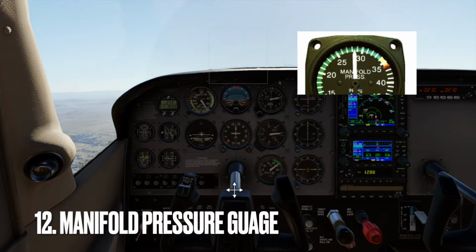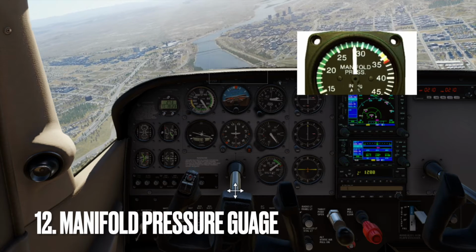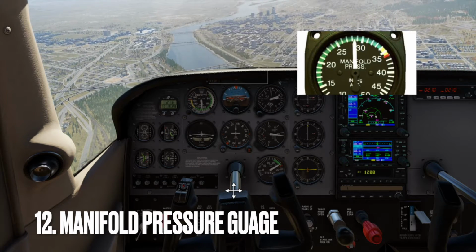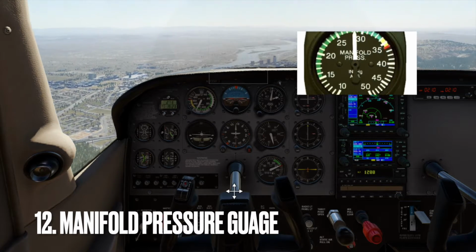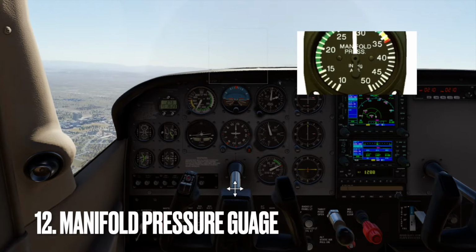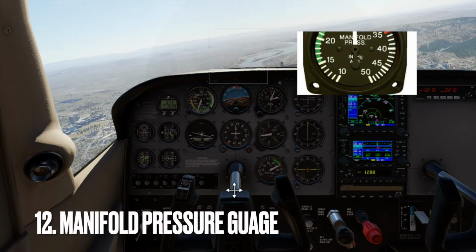The manifold pressure gauge shows the pressure of the air-fuel mixture in the engine's intake manifold. Pilots use the manifold pressure gauge to adjust engine power and optimize performance during different flight conditions. For example, during climb, the pilot adjusts manifold pressure to maintain the desired climb rate while avoiding engine stress. Monitoring manifold pressure helps pilots manage engine power, fuel consumption, and engine performance.